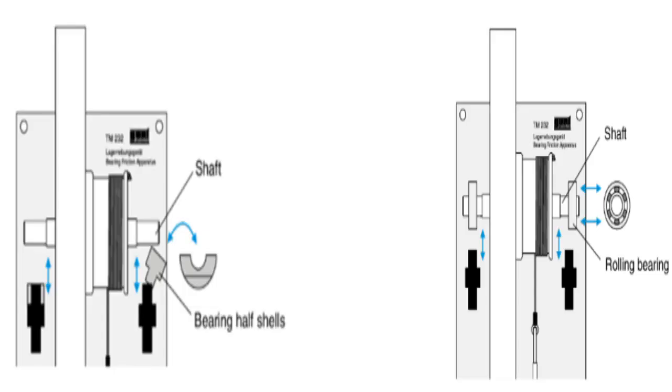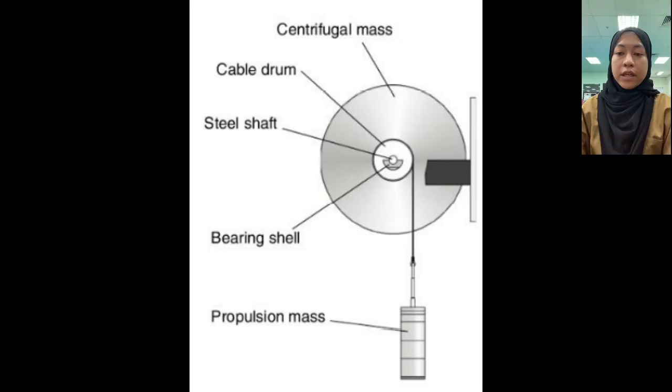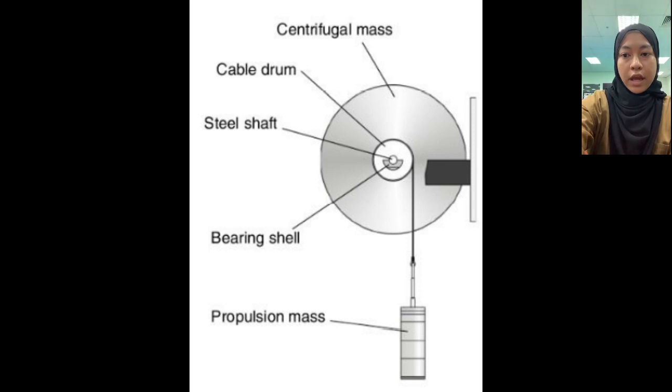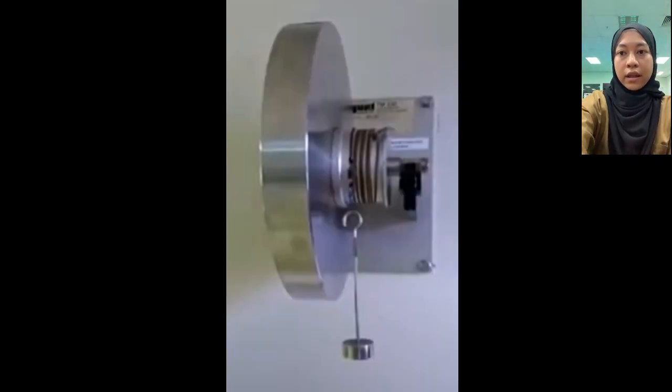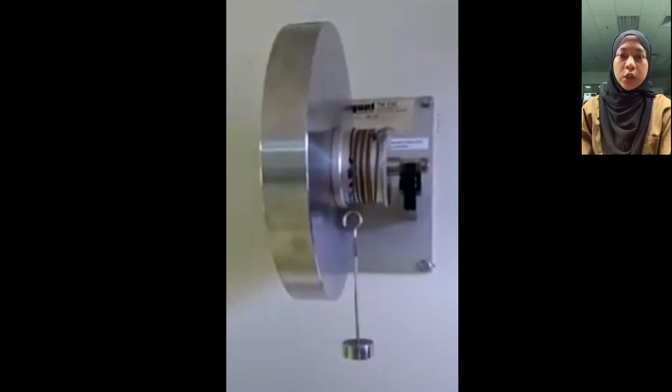Today I will explain about the procedure of the bearing friction lab. Firstly, we put the rope onto the rotating shaft, then we adjust the angle given. Secondly, we adjust the F1 or F hold to 50 Newton. After that, we rotate the rotating shaft until the data is shown and record the data. That's all from me, and I will pass to the next presenter to explain about the experiment.